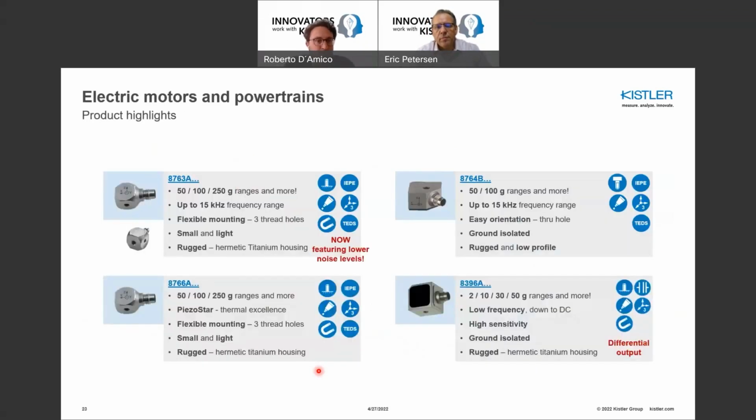So yes, I'm showing them in the pictures here. These sensors have smoothed edges to optimize. It's an optimal design to minimize the mass of the sensor. Plus, it is a way to optimize the usability of the sensor, because we've noted that a lot of damage takes place at the corners of the sensors. With this, we make the dismounting and mounting process a little bit safer for the sensor itself. So these are the two reasons why the corners are smoothed.